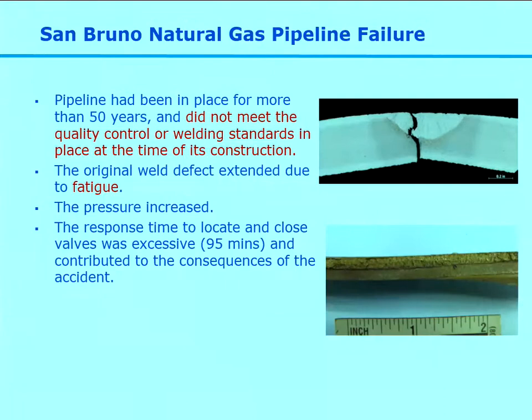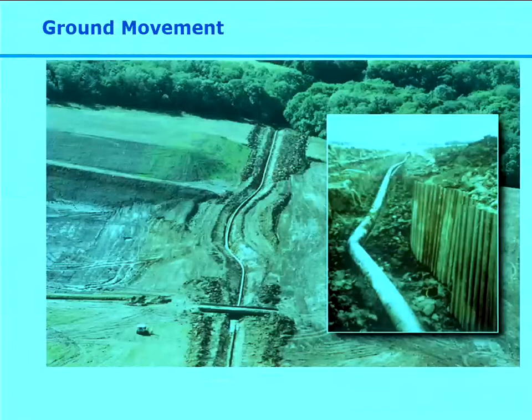What had happened here was the landowner knew that the pipeline was routed through his land, but he wanted to create a massive landfill site. So he excavated that, and he very carefully went and dumped all of the soil on the other side of the pipeline. The soil became unstable and it slipped, and it took the pipeline with it.